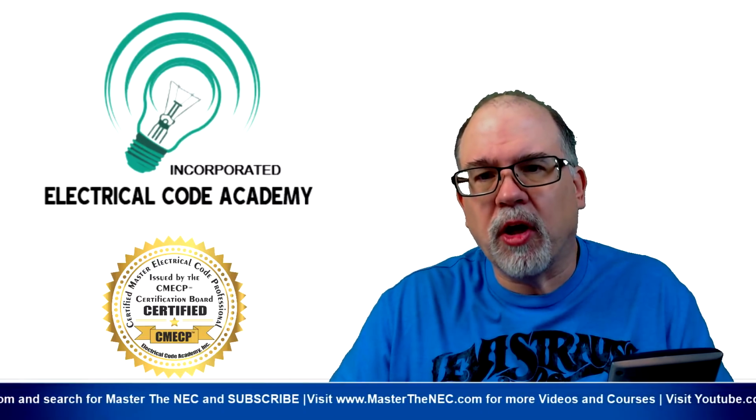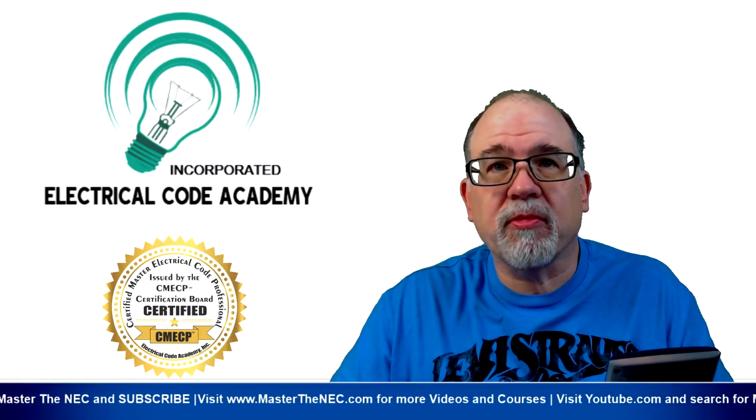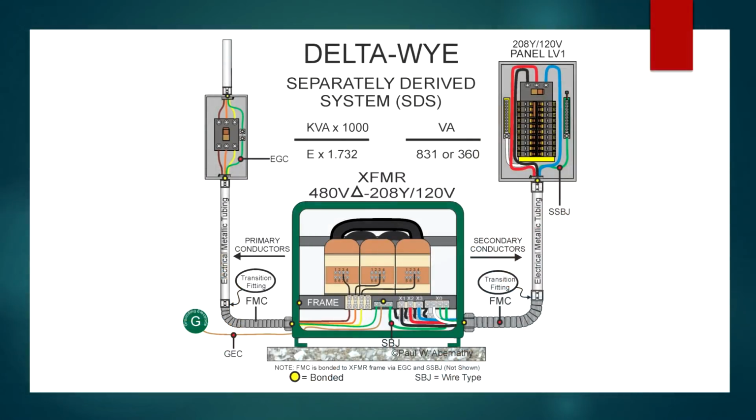All right, so if you go back, you'll see that I actually give you some shortcuts for that in the presentation, some things to keep to memory. So anytime you're dealing with 480 volts, just remember 831. That's all you have to remember. So it would be whatever the kVA is times 1,000, because we need to convert it to VA, and we divide that by 831. And that's just a shortcut to get you there.